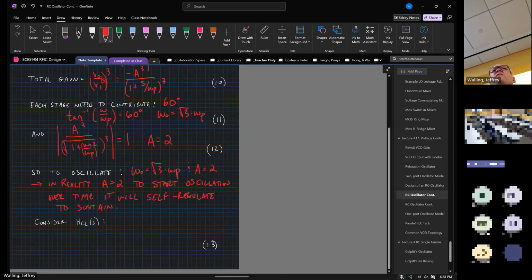Most of the time, how do you start an oscillator up? Attach an antenna to the PCB so that you pull signals in the environment into the loop? It's usually good enough just to turn the thing on. The transient will generally kick it over and start it up. Not always. If you designed it well, that's enough.